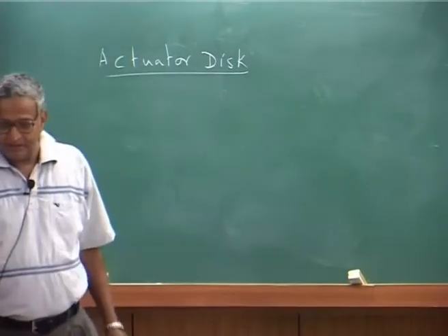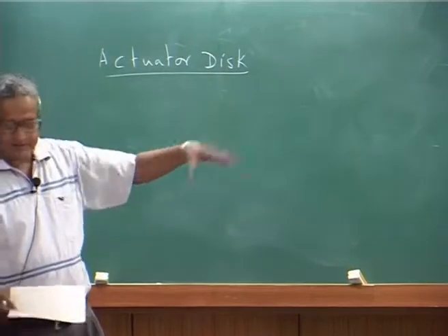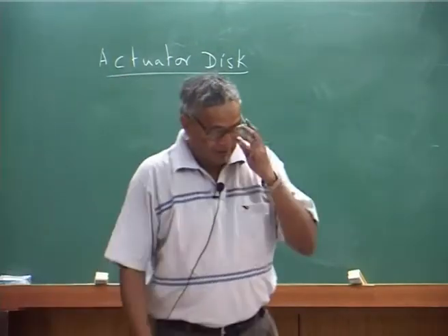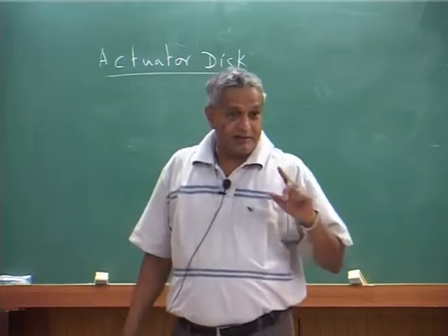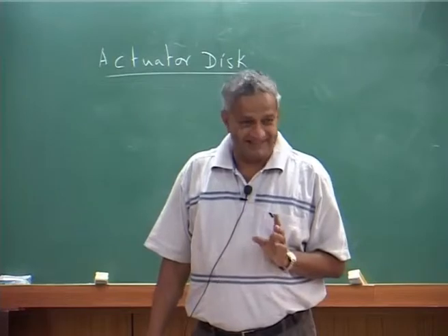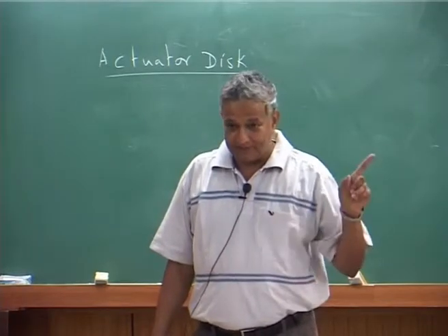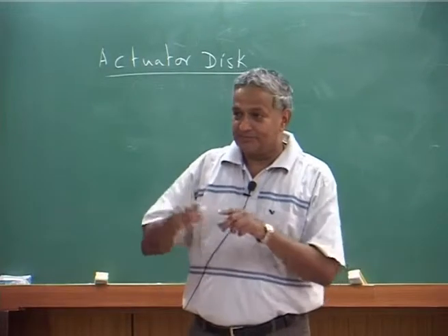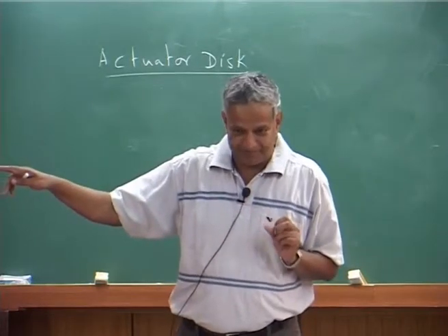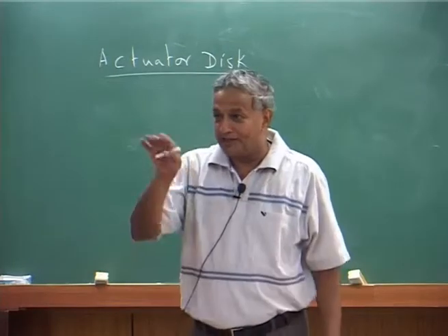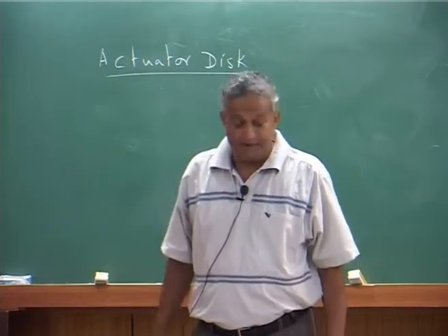Momentum theory does not give you the variation. Here please understand, you don't start using the differential momentum theory we derived in the class, that lambda i, which is a function of the blade pitch angle at every section. We had that sigma A over 16 etc., right?